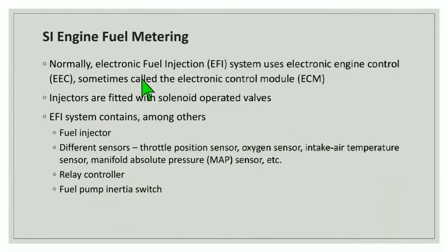Normally, an electronic fuel injection, EFI, system uses an electronic engine control, EEC, sometimes called the electronic control module, ECM. Injectors are fitted with solenoid operated valves. The EFI system contains, among others, fuel injectors, different sensors such as throttle position sensor, oxygen sensor, intake air temperature sensor, manifold absolute pressure sensor, MAP, etc. Relay controller, fuel pump, inertia switch.